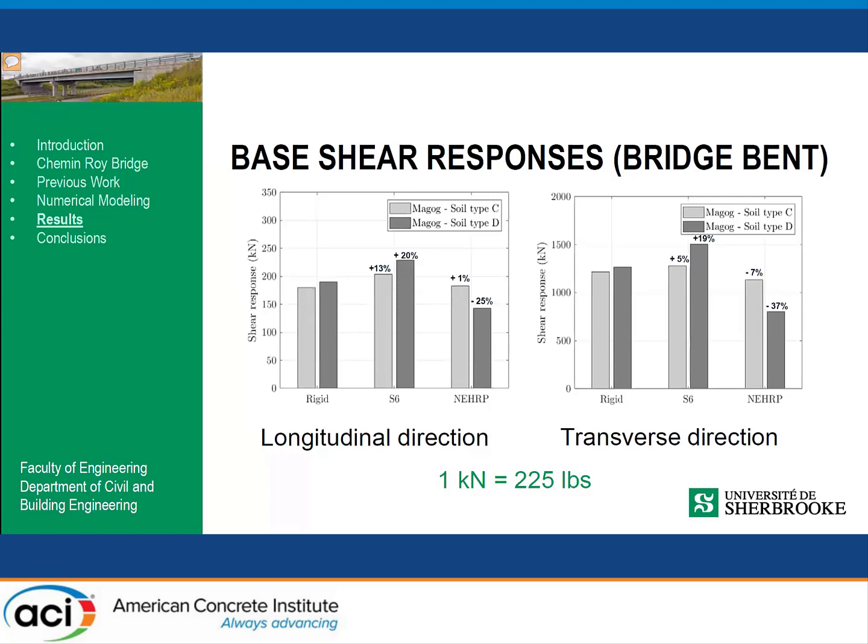And the period will increase when the foundation models are introduced. But for this bridge, particularly, the measured vibration periods are located along an upward slope of the mean spectrum. So this is why we see an increase in the shear response when we add the SSI model. But again, when you consider damping, it goes down.